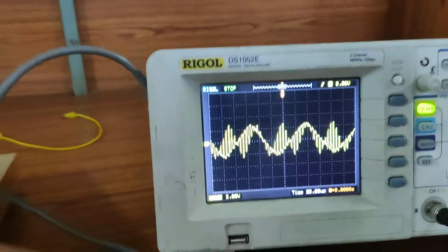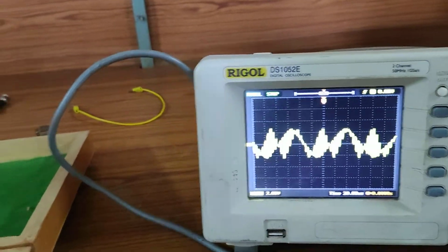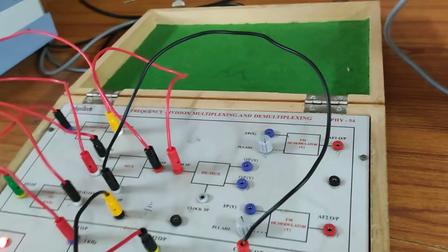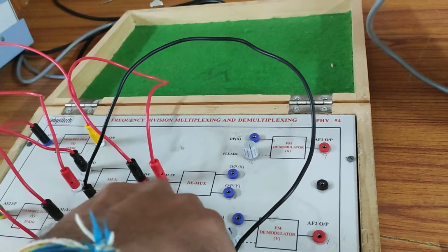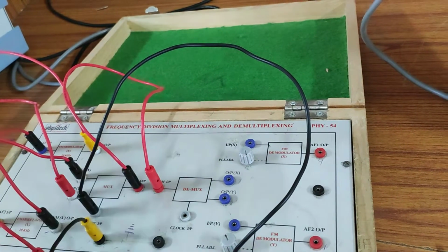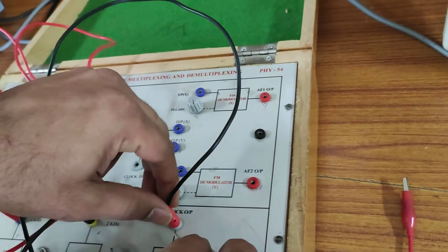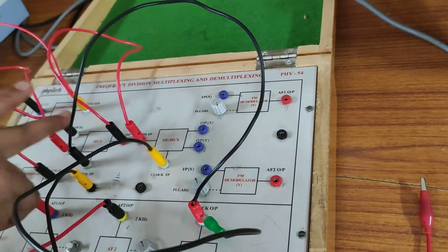And now let us see the operation of the demultiplexer, how it works. The definition of demultiplexing is nothing but, for the given one input, it makes 2 power n number of outputs, and the same clock pulse needs to be supplied here so that we get synchronization with the transmitter.